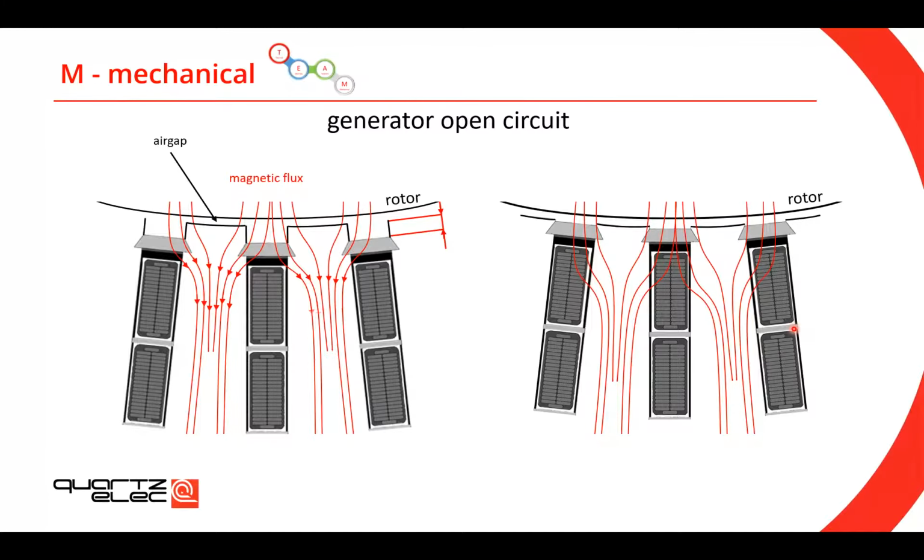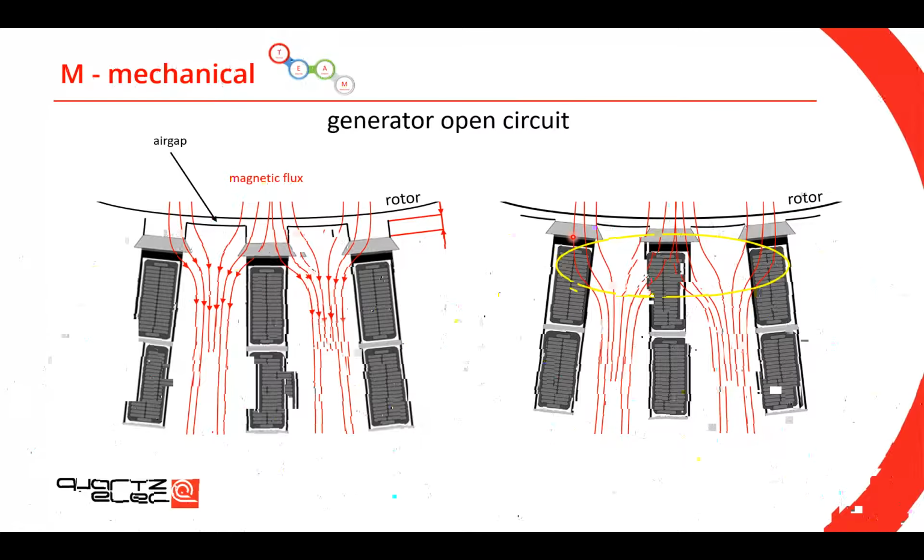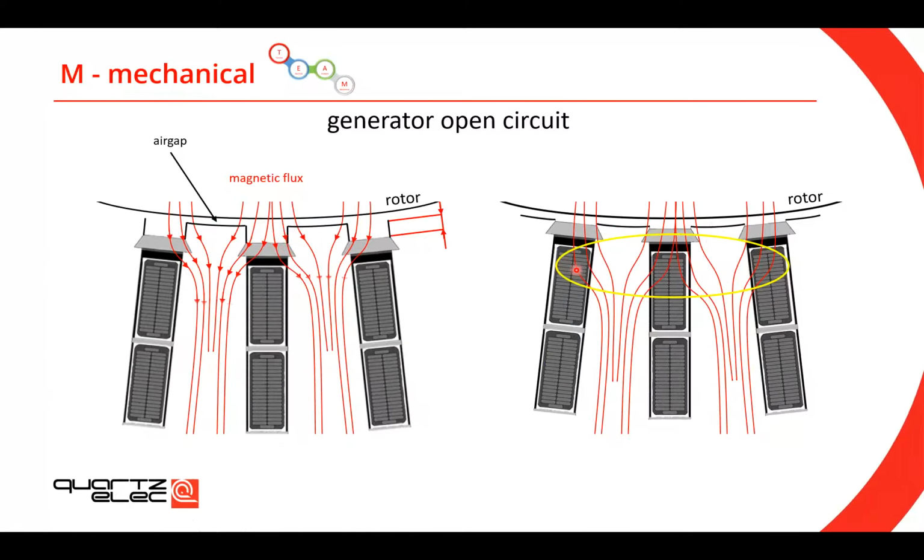Now, let's see the scenario when the stator bars don't sit as deep as the example on the left-hand side. You can see here that the magnetic flux will be passing the top stator bars, causing that side-to-side vibration. And that mechanical vibration will obviously deteriorate your insulation.